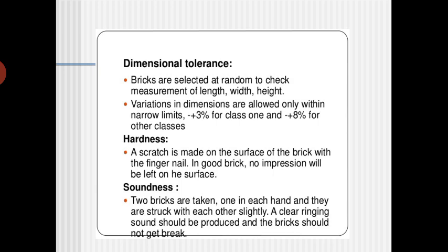Sometimes this extra hardness of bricks is not good for construction. Normally, if it is too hard, there are many chances that the disintegration will be faster, and it should not be too smooth either. So make sure that no impression is left on the surface of the brick. That we can call the hardness test.